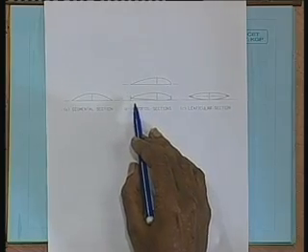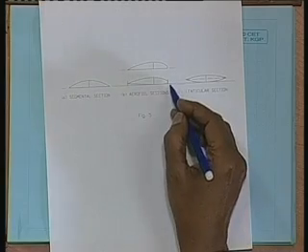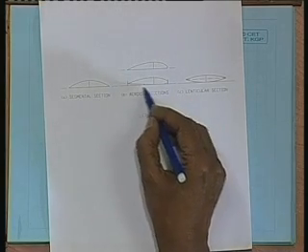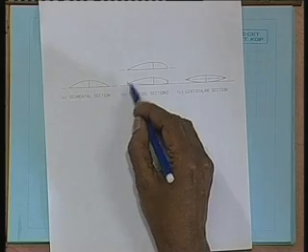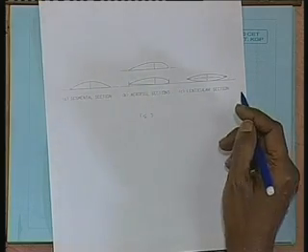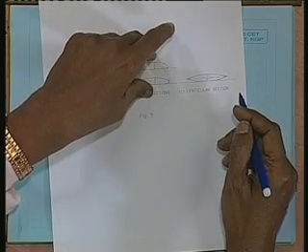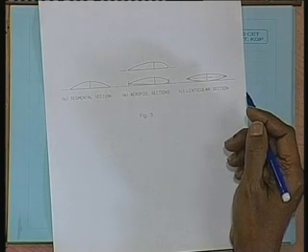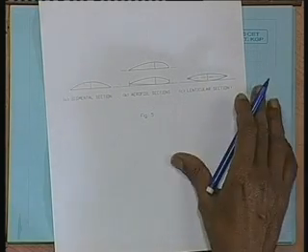So, you can also decide which way the propeller rotates by just looking at the propeller, if it has the aerofoil section. Now, as we have seen earlier, you can also give some offset to the face from the straight line, and still it would be an aerofoil section. This is the most commonly used section for the majority of propellers available in the world.